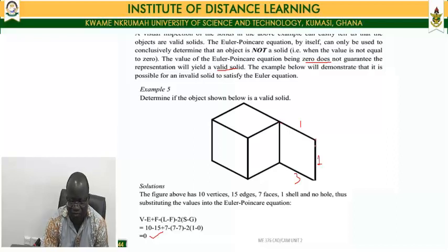This cannot be a proper vertex either. This also cannot be a proper face because this face must not interpenetrate. When we look through here, we should not see through. If we don't see through these two, then it means that this side has to be a double edge, which means it's a solid. So with this strip around here, this fails to be a face too.